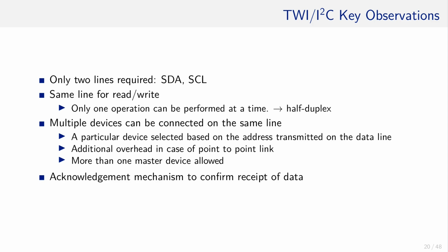That is not possible in UART, as the receiver has no method to tell the transmitter that the data has been received successfully, or if, for instance, bit flips occurred. On the other hand, I2C does not support parity, which then needs to be implemented in software if required. That's all regarding the addressing.